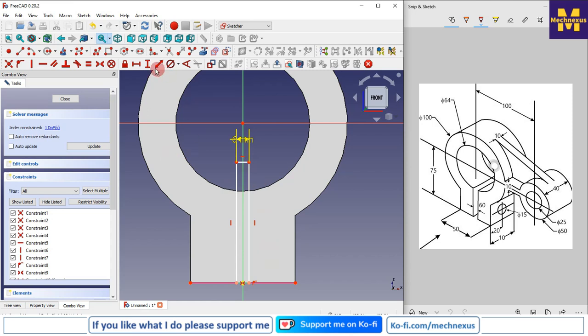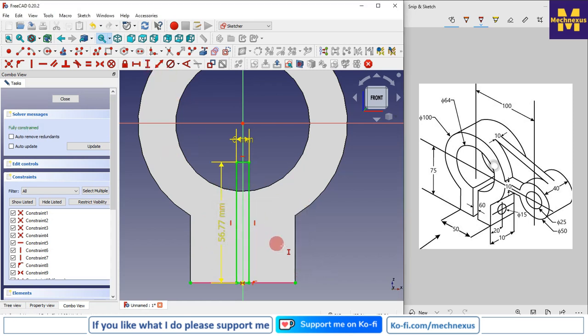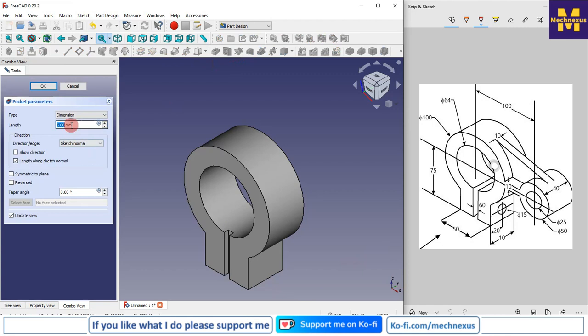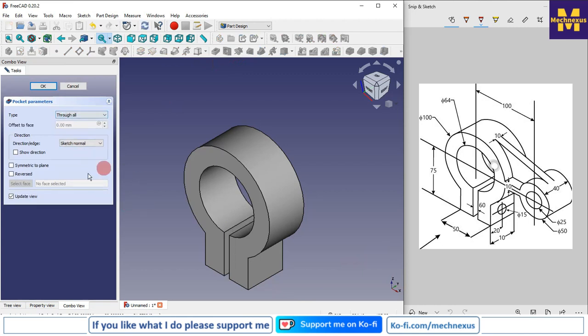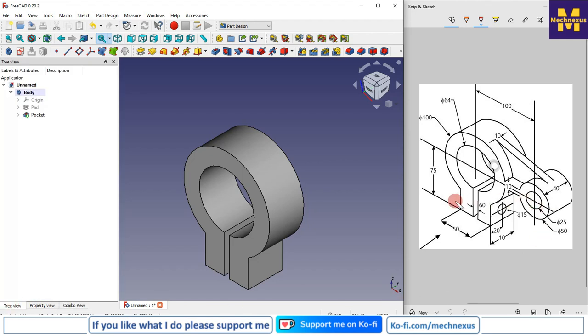Height is not important because after all we are going to remove the material. So I will close it, and I will go with the cut, and I will say through all. So as an engineer you must have the ability to read the drawing and also find out the mistakes in the drawing, like I have done here.